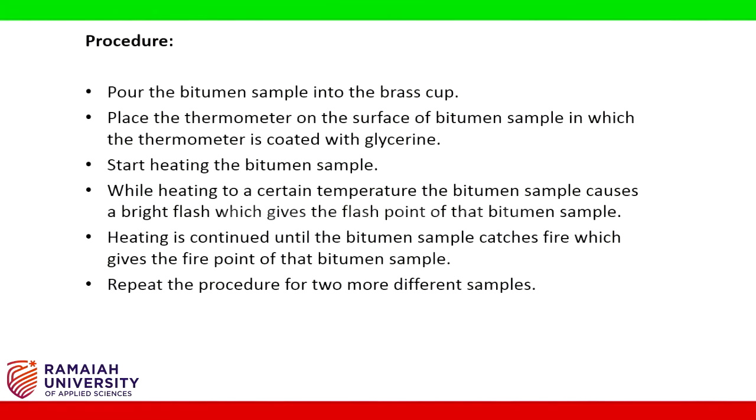Procedure: pour the bitumen sample into the brass cup. Place the thermometer on the surface of the bitumen sample, in which the thermometer is coated with glycerin. Start heating the bitumen sample.